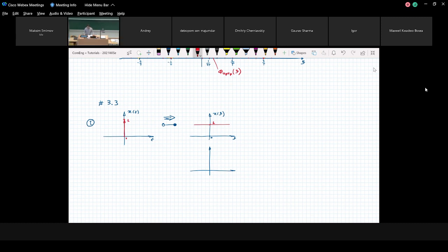If you calculate the square of it, it will be the same line. But this plot corresponds to the energy spectral density. It's not the spectrum, it's the energy spectral density, Sxx of f, which we find as the absolute value of X of f squared.